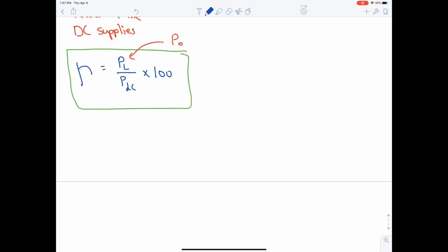Okay. So another equation is for finding the power dissipated in the amplifier. The power balance equation is as follows: P_DC plus P_input equals P_load plus P_dissipated.